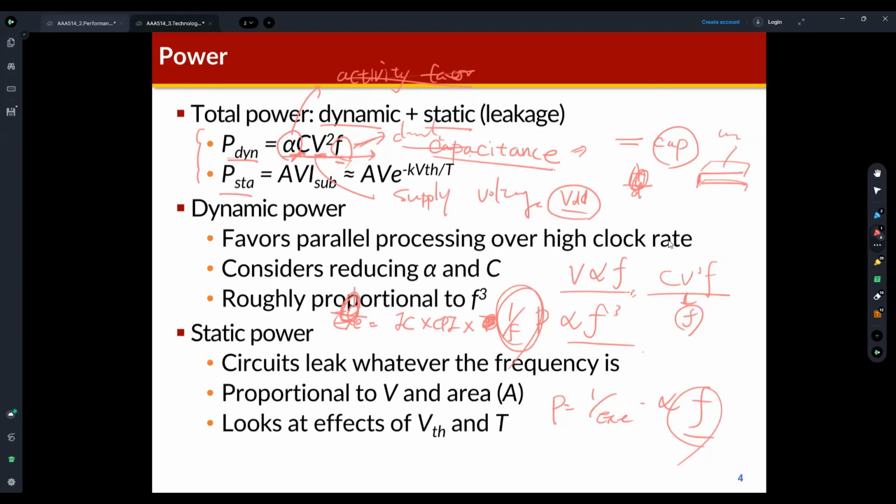Way to increase the performance of a processor. But in order to increase the performance by F, the dynamic power consumption of the processor is increased by F cubed. So that's very critical. That's why we cannot apply very high performance single core recently, because I said the easiest way to increase performance is to increase the clock rate, the clock frequency.